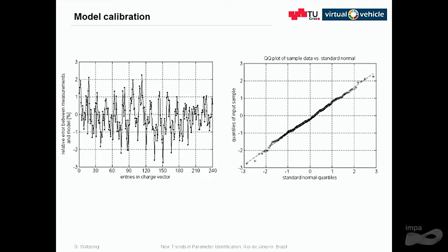That's typically, I know it's an engineering word, but for a certain stage, we have to come up with a match of the virtual world and the real world. And we have to work out, and usually you do it like this. You calibrate your model, or you fit your model, so it's more or less an optimization task for an empty tube and an empty simulated environment, and then you define a certain phantom, like a centered circle or two circles in there, and you, let's say, fit your model exactly to this new internal setup.